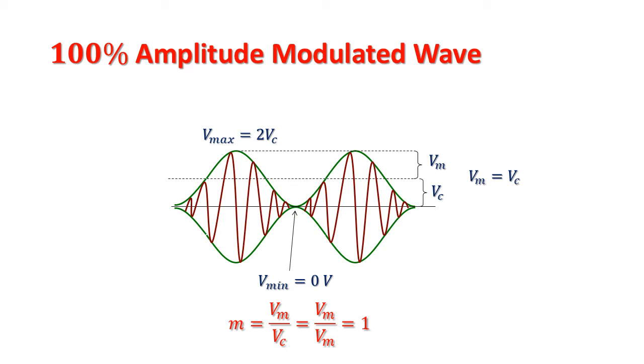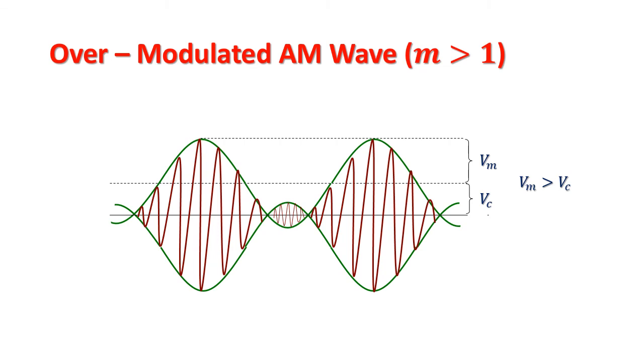During the modulation process, the carrier power remains constant. It is only needed as a reference during the demodulation process. This means that the sideband power is the useful section of the signal, and this corresponds to only 33% of the total power transmitted. If the level of modulation is more than 100%, this causes what is termed overmodulation.